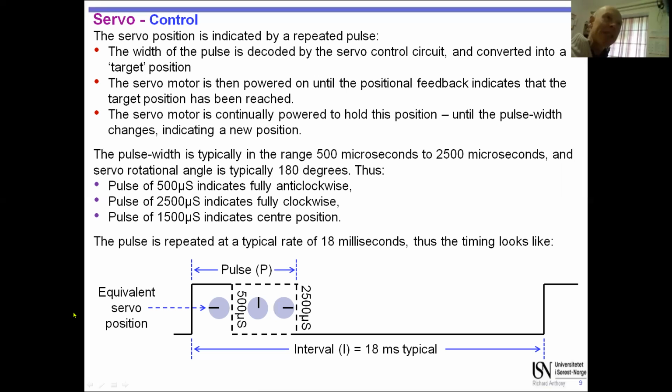Obviously, that's where testing comes in as well. But if I say to you, this is moving from there through to there, and I call that a clockwise movement, then you've got to be careful when you interpret this. Is that looking up the shaft or down the shaft of the servo? Things like that you may take for granted, but the engineer who's got to build this may get very confused. So there's always these terminologies.